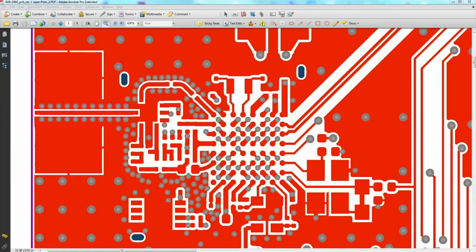Now, because many of the aforementioned items can affect transmission lines, EMI problems can occur. To reduce these problems, good PCB design is important, and with some simple design rules, the PCB designer can minimize these problems. A good PCB layout starts with the circuit design. Do not postpone considerations about the layout. One of the most important aspects affecting the layout is the location of each functional block. Keep their devices and their traces together.